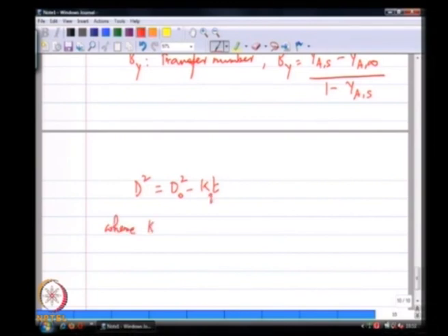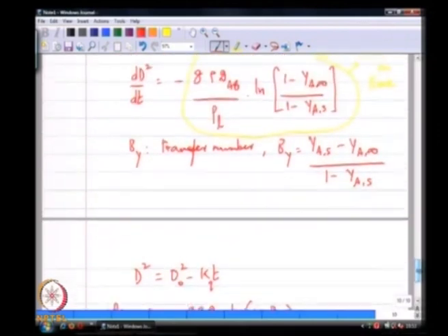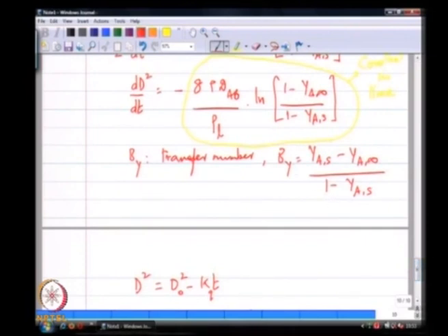I will call this Kq, I will tell you for quasi steady. Kq equals, you can easily show that with this definition of B, what is inside the argument for the natural logarithm is nothing but 1 plus B. So, when the saturation humidity and the humidity at infinity are equal, saturation mass fractions and the vapor mass fraction far away are equal, your transfer number is 0. Okay, that is like saying I do not want any mass transfer to happen.